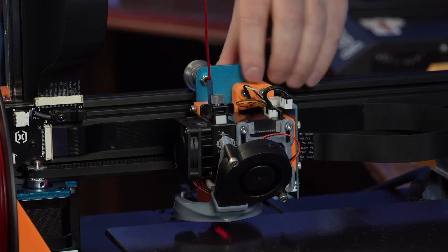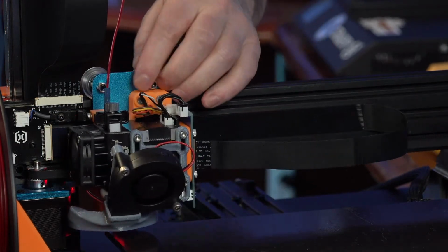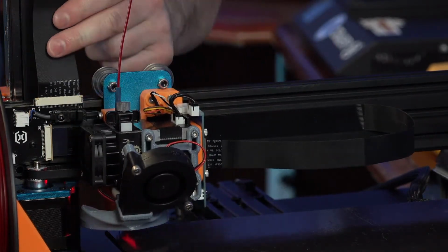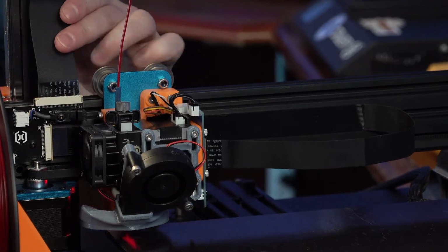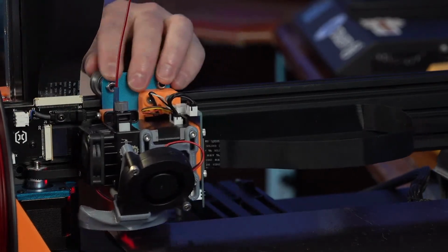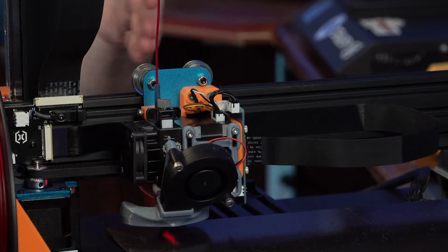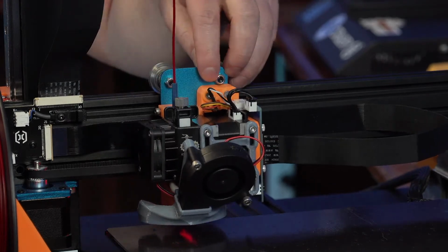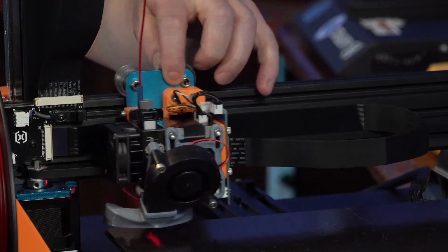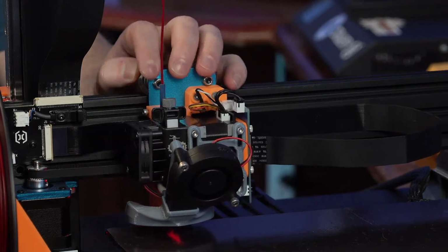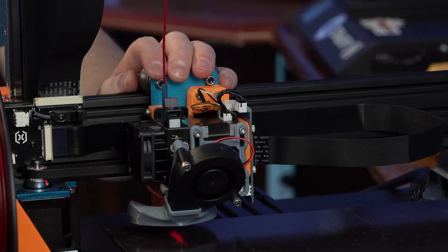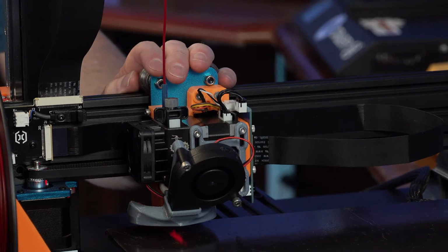Okay. So what this does is it triggers the end stop. There's a little inductive end stop. And another nice thing about it too is if you wanted to dial in your offset from the end stop, you could screw it in, unscrew it, and that changes where you could have this by a few millimeters if you need to. So. And I missed it. Andrea answered that for us. Oh yeah, because he'd done that too.